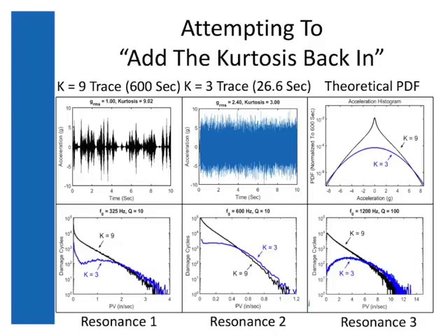If you want to increase the kurtosis of that blue trace, if you don't change the total GRMS level, then you are going to extend that bottom right intercept out beyond the test that you were replacing, and that will legitimately be an overtest. Yes, you'll test faster, but that's a real overtest. If you don't want to move that bottom right intercept, but you want to increase the kurtosis, what you end up doing is just shoving more and more of the damage cycles down to lower pseudo-velocity, and so you're going to have to run longer to achieve the same damage.